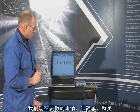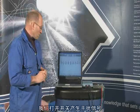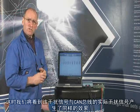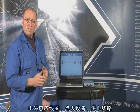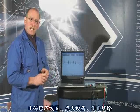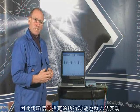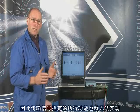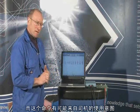What I'd like to do, just briefly, is let you take a look at this and then switch a glitch in. And what you're going to see is the same effect as if there was a genuine fault within an automotive CAN network. These sort of faults are brought about by inductors, coils, ignition devices, power seats, anything that has a fair amount of current running through them that's being switched very quickly, and it causes spikes or ringing on the CAN network. And if that happens, the CAN message then becomes corrupted and the intended functionality of that message is then destroyed. In other words, the vehicle will not demonstrate that command that's been intended by the driver.